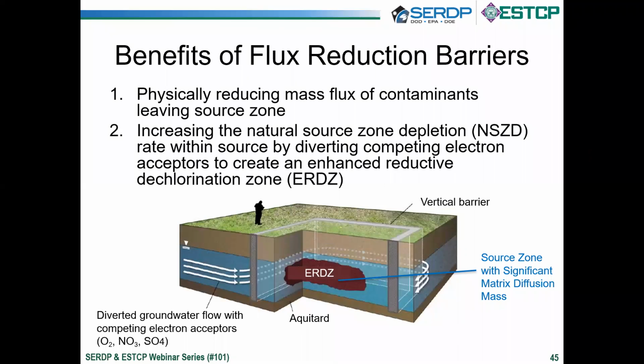Now, overall, the vision for this demonstration was really to adapt methods from the geotechnical world, where they use permeation grouting that allows grout to flow into the pore space where it can then gel or harden. And the remediation business also has a lot more experience with injection technologies over the last couple decades. So the goal was to apply these grouts using our standard injection technologies to see if we can implement barriers more effectively.